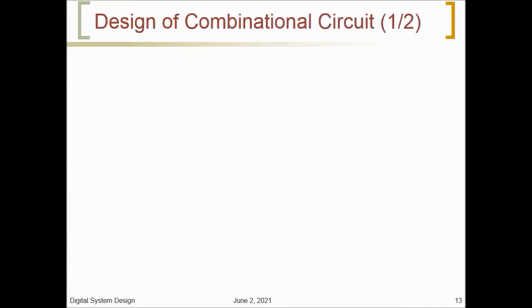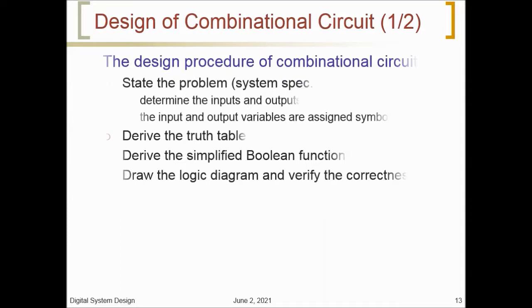Design procedure of a combinational circuit. The design of combinational circuits starts from the specification of the design objective and culminates in a logic circuit diagram or a set of Boolean functions from which the logic diagram can be obtained. The procedure involves the following steps.